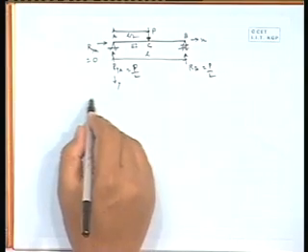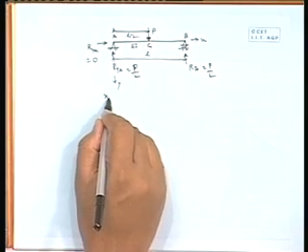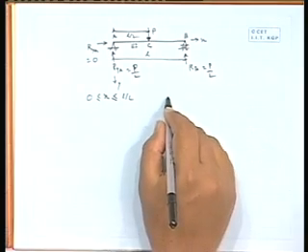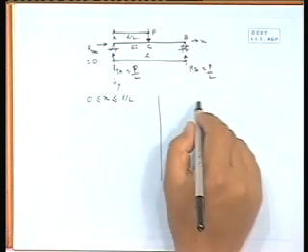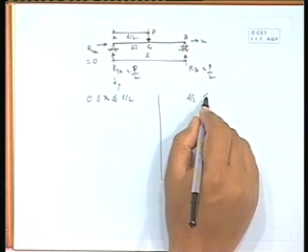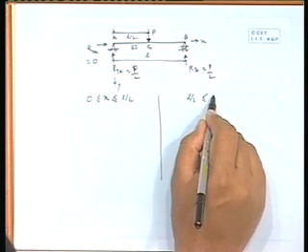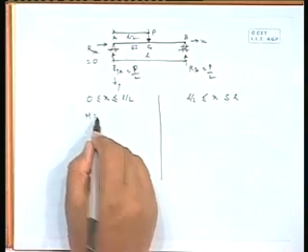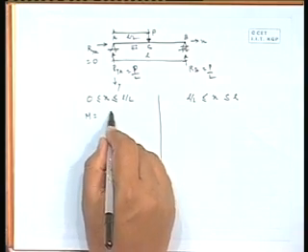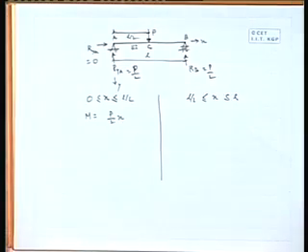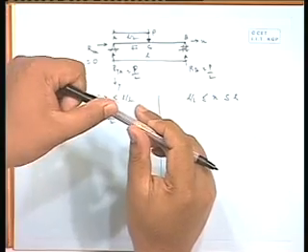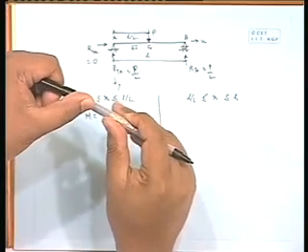Right. So, if we divide into two regions, say x from 0 to L by 2 is one part, and another part is L by 2 to L. Here your moment is P divided by 2 into x, that is all, because P into the distance is giving a sagging type of moment, positive moment.